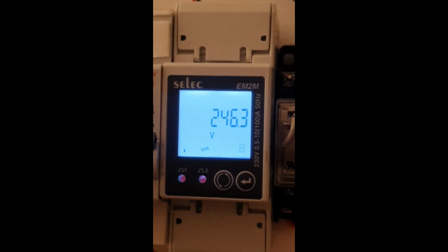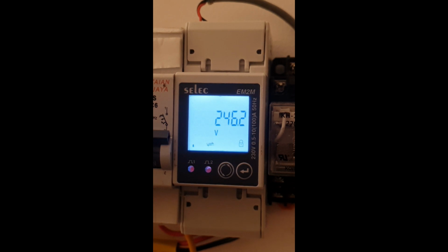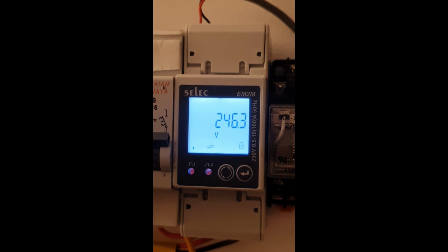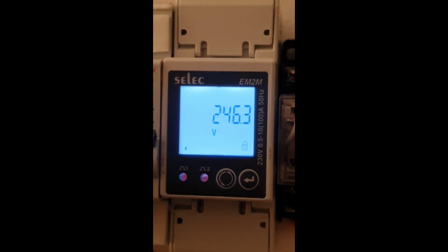This is the meter which I am using at my home, and it can be used to measure many electrical parameters such as voltage, current, frequency, power factor, active power, reactive power, and active energy, and almost all the electrical parameters can be measured with this. And the measured data can be transferred to any third-party system over the serial communication. This is the serial communication which is running on RS-485, and the protocol which is used is Modbus RTU. So Modbus RTU is an open protocol and it can be integrated to any third-party systems.